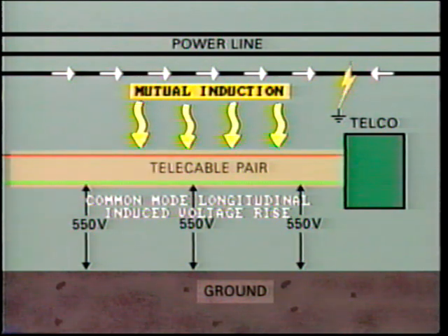The difference in potential between conductors does not change, but both will rise in relation to ground. Current flow through the sheath will increase greatly, causing damage to the cable if conditions persist. These are short duration surges, as power line faults are usually cleared in less than a quarter of a second.